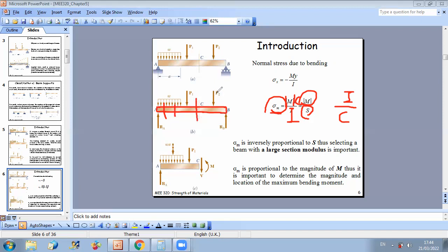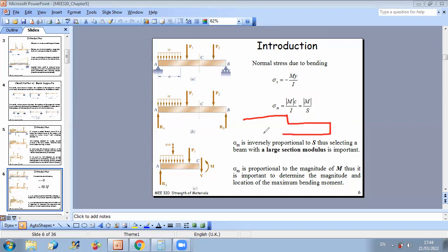So at any cut, you have the same cross section. So this parameter is not changing. This is a first advantage. This will simplify the analysis, because then we can just say that maximum stress corresponds to maximum moment over the whole beam. However, if you have change in cross section, the analysis will become more complicated.